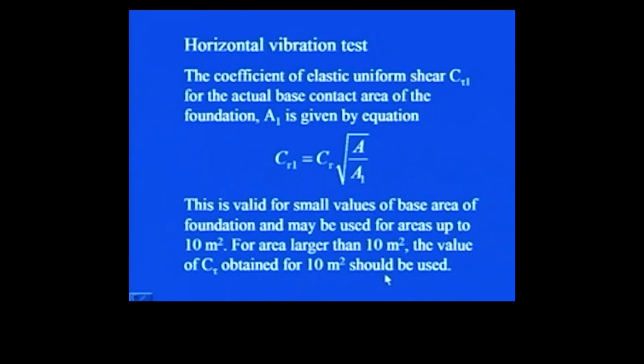So, as the case was there in vertical vibration test, exactly on the similar lines, here also the area restriction of 10 meter square is there. So, in case the foundation base contact area is more than 10 meter square, then you have to take that area value as 10 meter square and then go ahead with the further calculation.